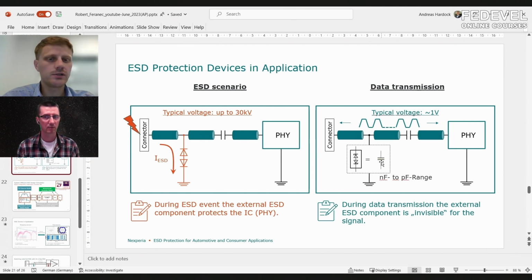Yeah, different simulations. For data transmission, we do have scattering parameters, so an S-parameter model. The touchstone file, for example, as some people know, you can use those files and that data in most of the modern solvers and tools, so ADS or CST or HFSS or a lot more. Most of them can handle this IEEE standard, this touchstone.